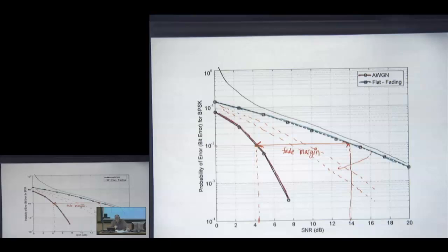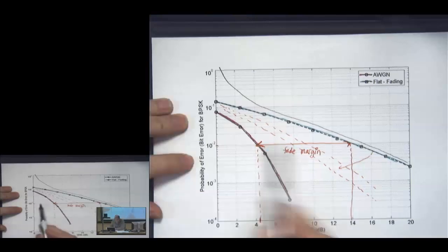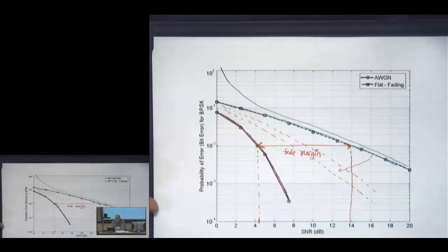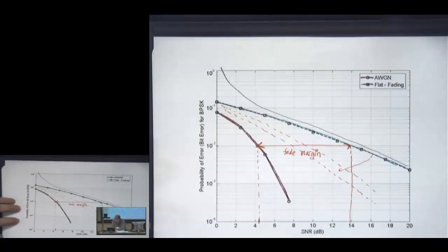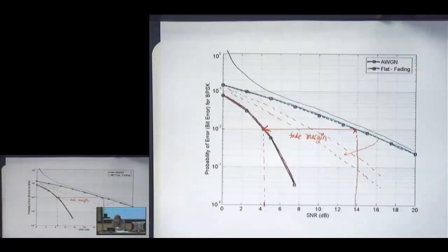So again, the main summary here is, first, to be able to calculate this bound on the probability of error. You have to define Rayleigh fading, and then you should be able to evaluate their performance, compute the fade margin at a given target probability of error, and then we'll combine this with some of the other large-scale calculations. And that's going to be what's called link budget analysis, which I think we do next Wednesday.